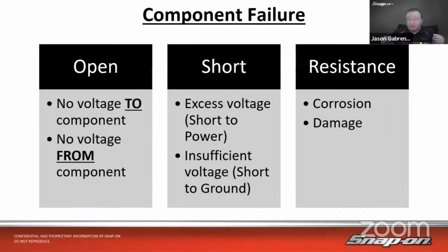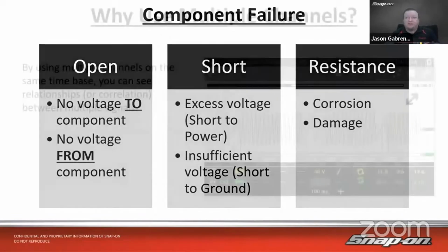Really, you need to load the circuit, ideally. So maybe like a headlight or something like that, a lot of folks use. But you might also be able to tell by doing a voltage drop and seeing where the voltage drops off in the circuit. So these are the ways we can test.